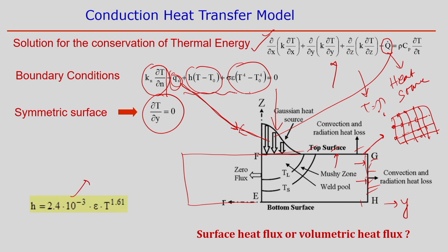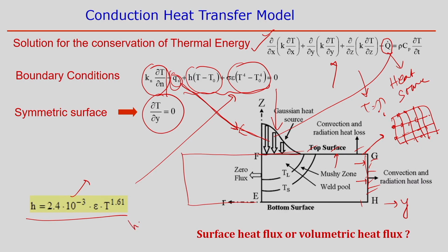And here also there is another part, the H. So, here if you see the convection and radiation, the finite element discretization can be different, because here there is the temperature variable to the fourth power. So, in that case we can take the combined effect of convection and radiation, with the simple equation H equal to in this particular way, and then you can make it equivalent to an effective heat transfer coefficient that accounts for both the convective heat transfer from the surface as well as the radiation effect. Both can be combined there to find the effective heat transfer, such that the final H will be the effective heat transfer times T minus some reference temperature.